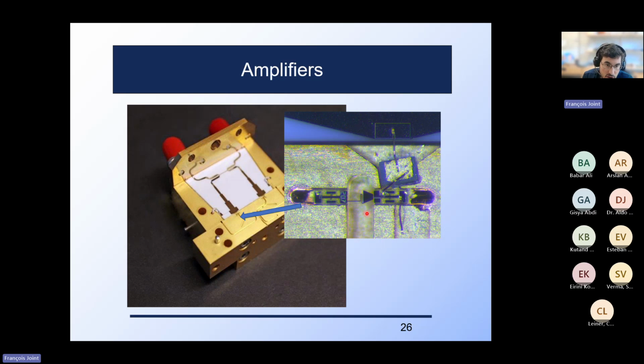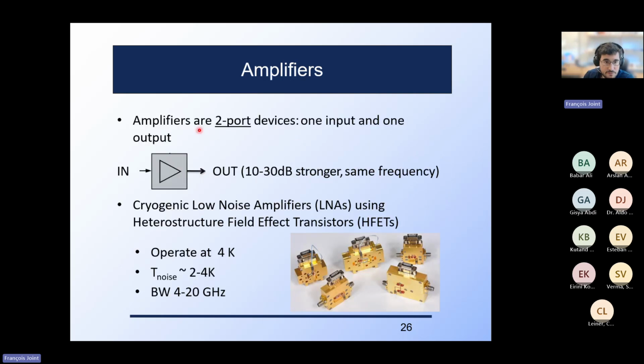And also we provide on the same PCB this 90-degree hybrid, the hybrid that allows us to recombine and split USB and LSB. So here we have the two mixers for one polarization, and here we have the output of USB and LSB. So that's right before we can finally amplify. After these two outputs, we can use HEMTs.